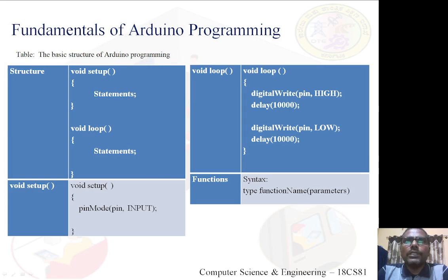So here, the setup function, listen carefully. The setup function is always executed only once. When you turn on Arduino, the setup function will execute only once.